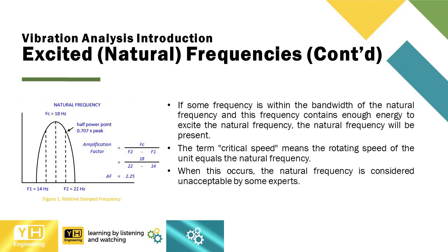If some frequency is within the bandwidth of the natural frequency, and this frequency contains enough energy to excite the natural frequency, the natural frequency will be present. The term critical speed means the rotating speed of the unit equals the natural frequency. When this occurs, the natural frequency is considered unacceptable by some experts.